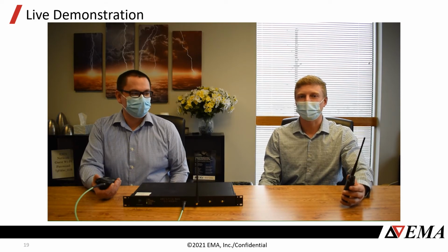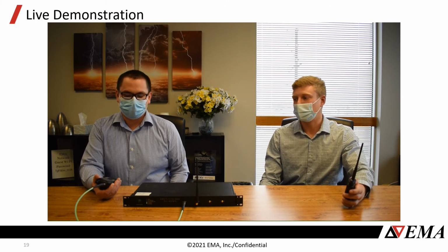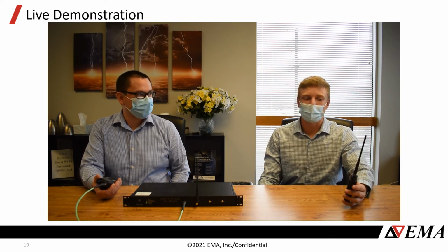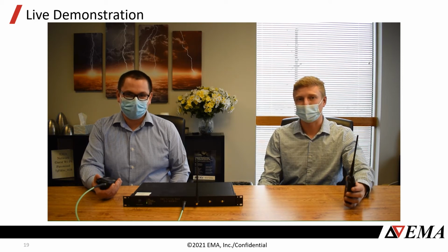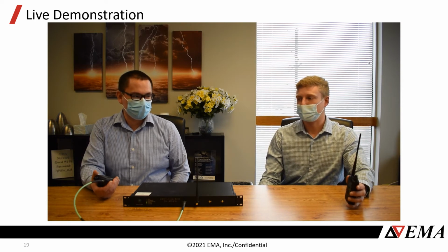This specific case of interference is unique because there's actually 2 signals contributing to the interference. We've hooked a low-pass filter up to the transmitter to block that third harmonic from getting to the receiver, but the fundamental of the transmitter actually falls into a mixer product for the receiver as well. So we're going to show that with this low-pass filter that we still get interference.